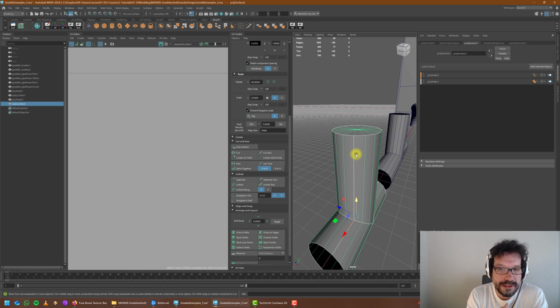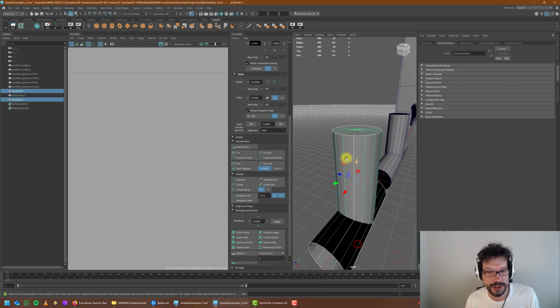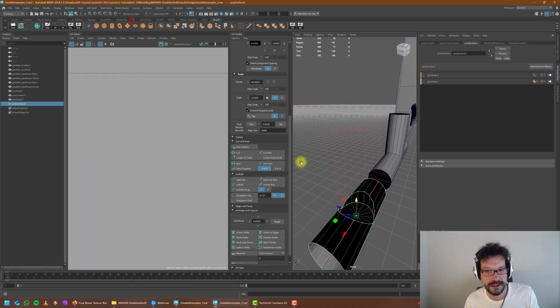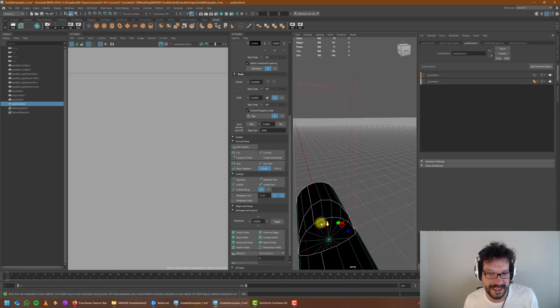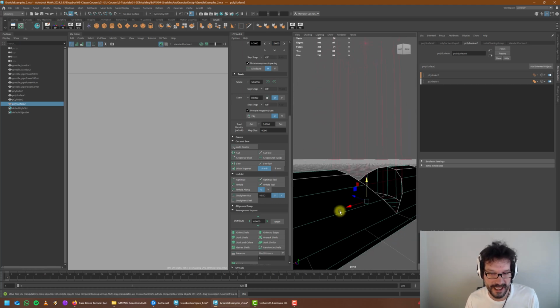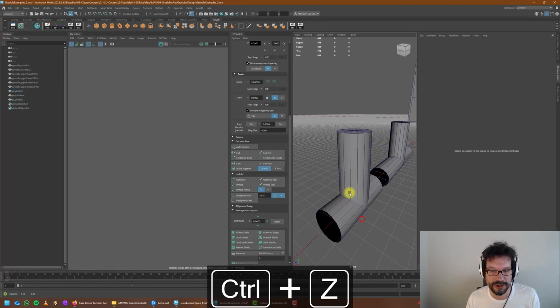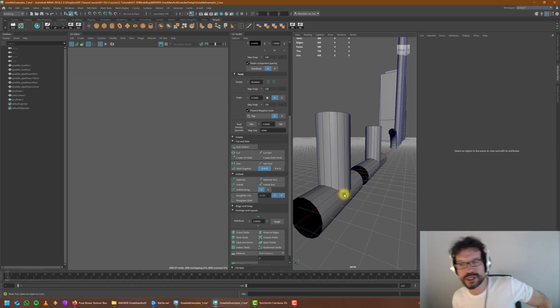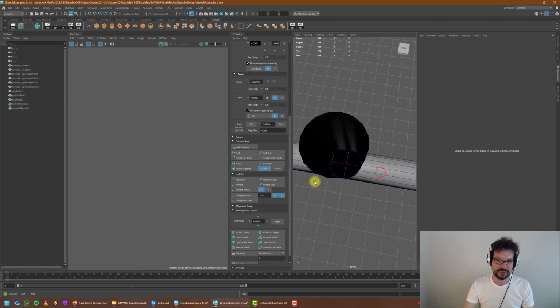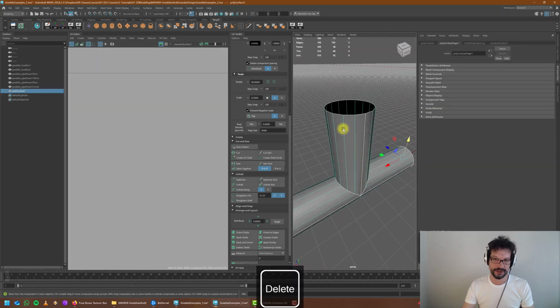If that issue happens, a couple of things might be wrong. First of all, for example, one of the objects might be facing the other direction. In that circumstance, it's definitely not going to work as intended. Okay, now they are unioned, but as you can see, completely inside out. So this could happen. Or like I said, an open object versus a closed object boolean might not work. In those circumstances, check your work. Maybe you have to edit the objects just a touch at first, and then do whatever it is you need to do.